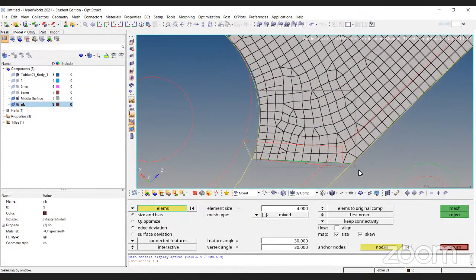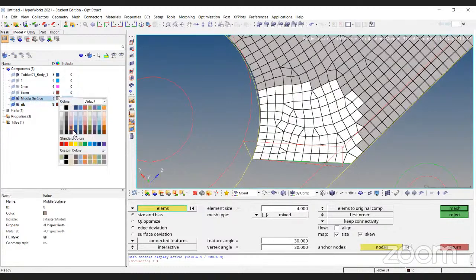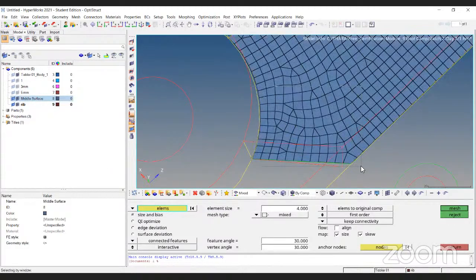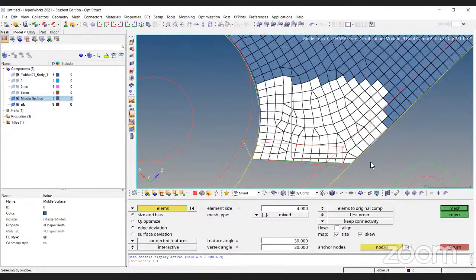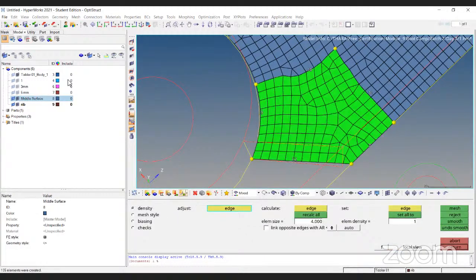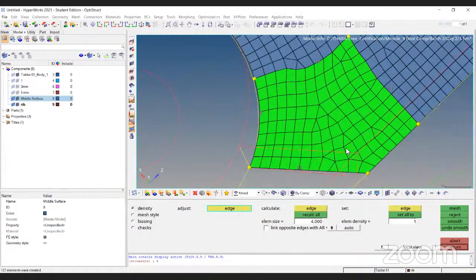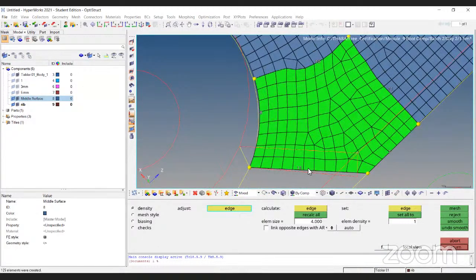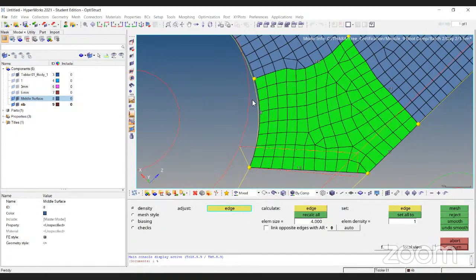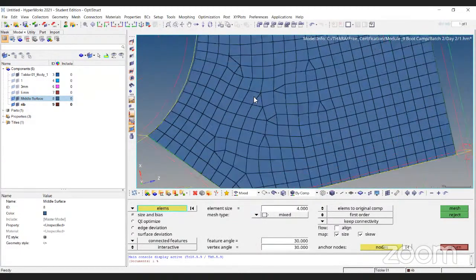See, just observe it. I'm selecting these surfaces to do remesh. Just I'm selecting these elements. You also need to select like this only. If you click on this one, this is called the density of the element. See, I'm reducing the density. Here also I'm reducing the density, and here too. Why? Because I'm trying to reduce the number of trias.